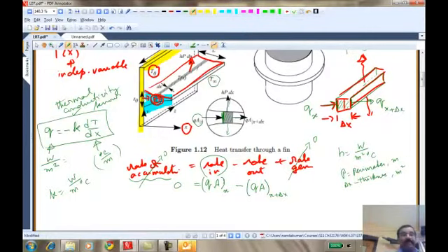Right? And you can very easily check, because Q has the units of watts per meter square. We're multiplying it by A, which has the units of meter square. So the product should have the units of watts or joules per second. Are we done? No. We have one more surface, which is at the top and the bottom.